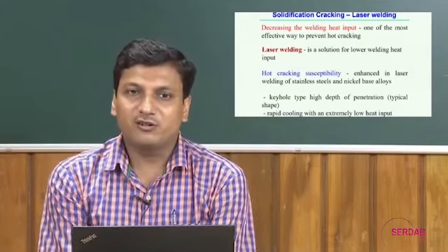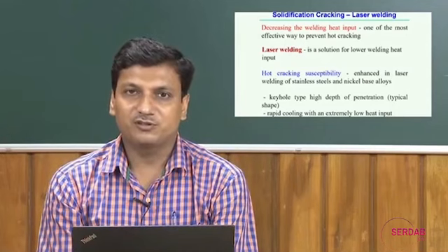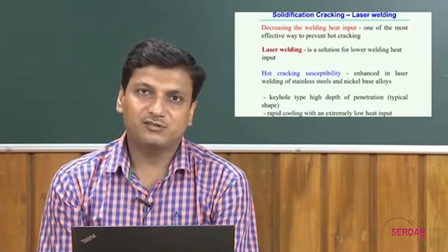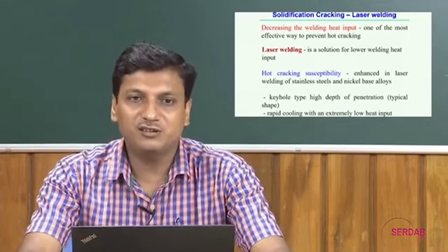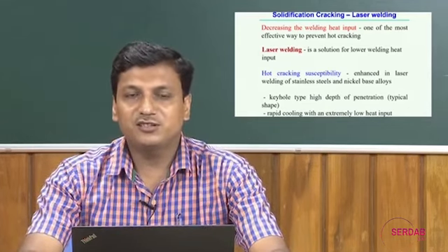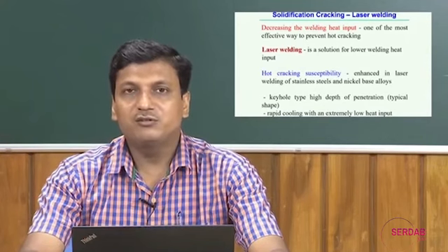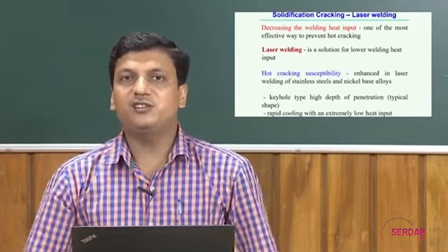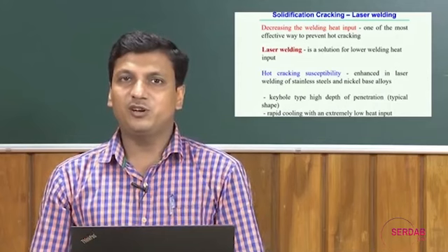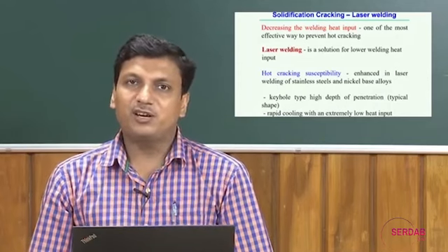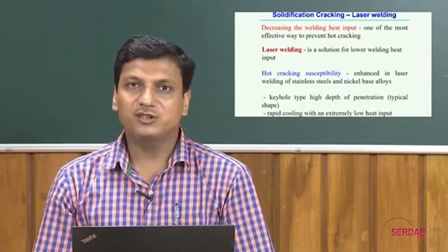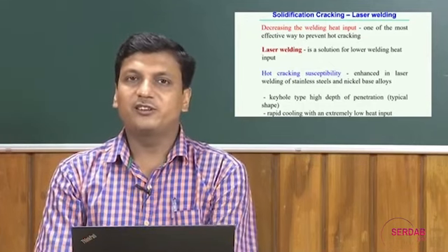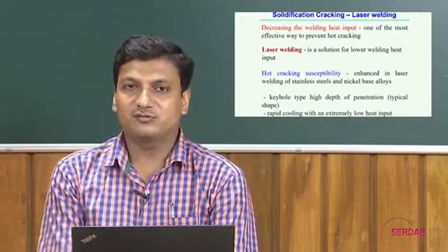solidification cracking or hot cracking phenomena in the laser welding process, if we do not use any precaution. In that case there is rapid cooling with an extremely low heat input. Normally in very rapid cooling, even at very low heat input, that sometimes promotes the hot cracking phenomena in laser welding processes.